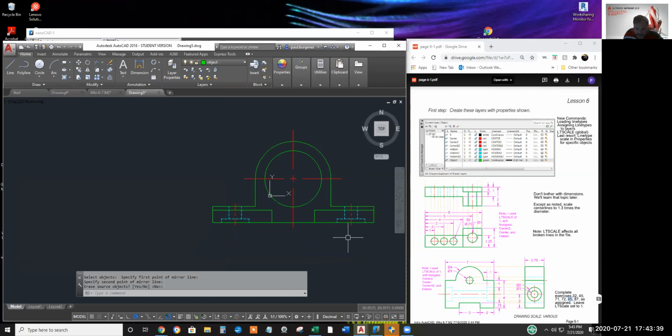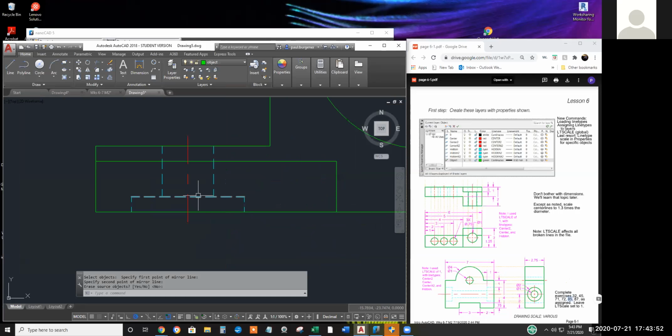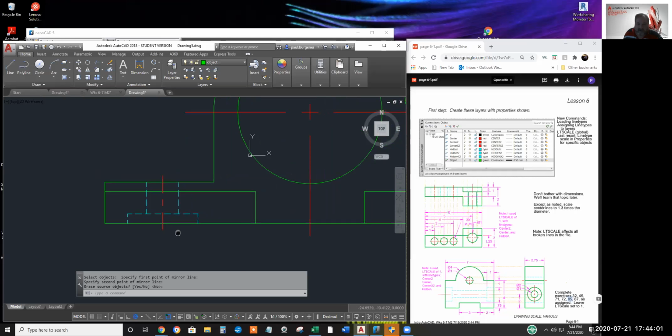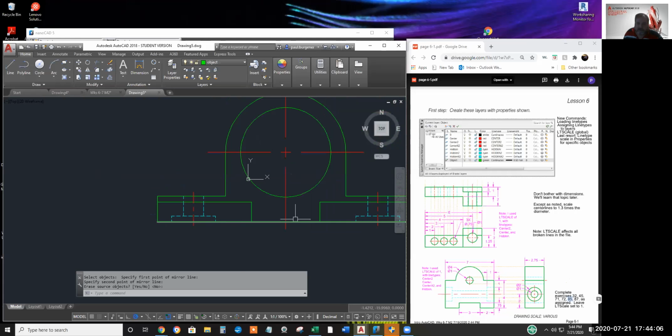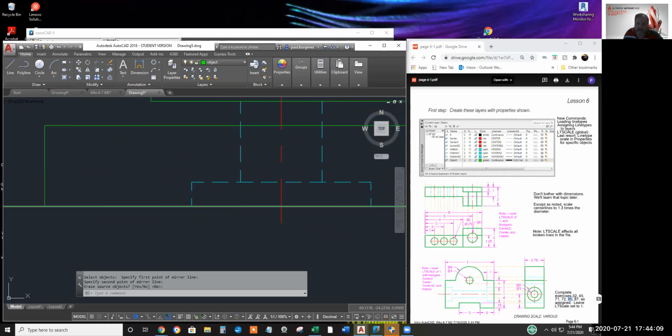See anything I'm missing? I think there's too much overhang on that. Okay. I think you gotta trim the horizontal hidden line. The book has these sections trimmed, but I believe the book is in error. I'm with you on that one, Paul. The book is in error. If we made this out of glass, there'd be a kind of washer-shaped surface that went all the way across.